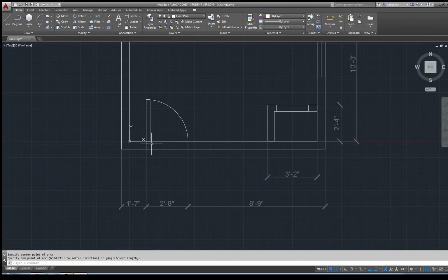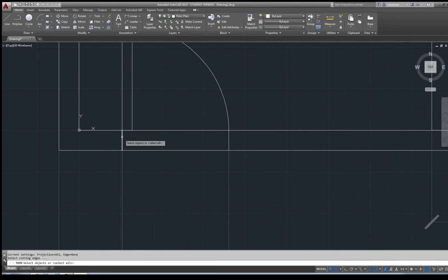Okay, now you see actually that visually it doesn't look like you could walk through. The wall looks solid, so we have to cut this one open. We can use the trim tool. Trim works the way that you select all objects that somehow touch or overlap, and then you can press spacebar and simply click on what you would like to remove, and the software understands what elements to cut away. And then you can press escape.